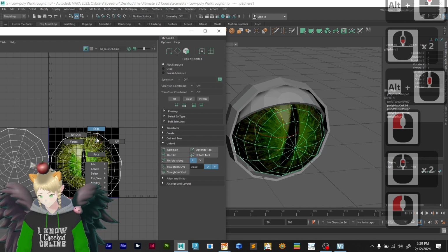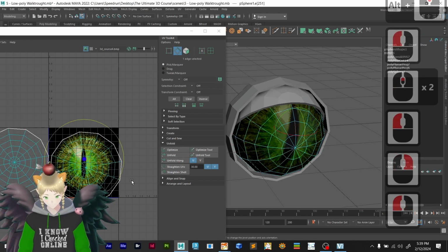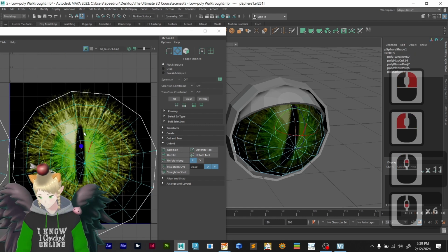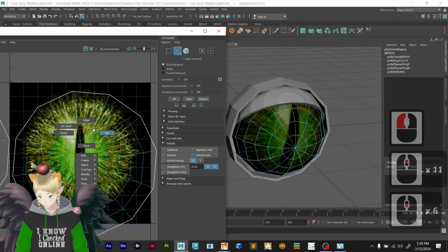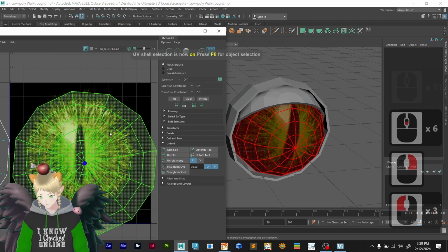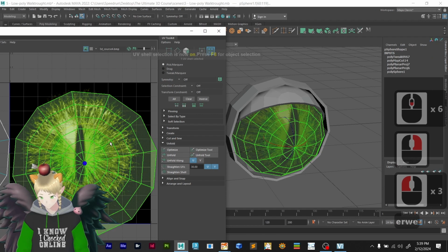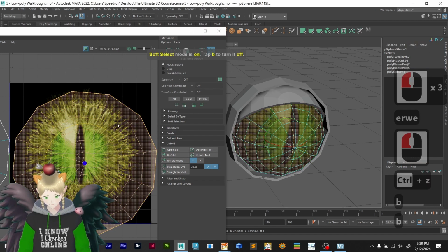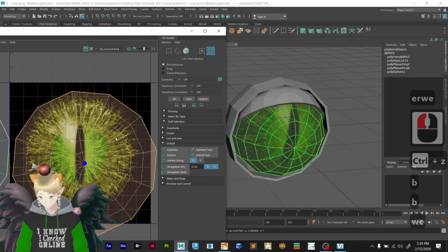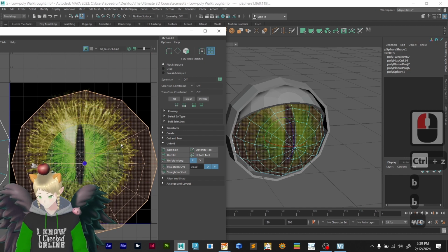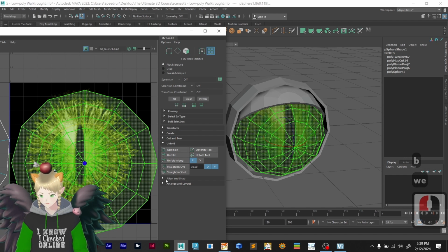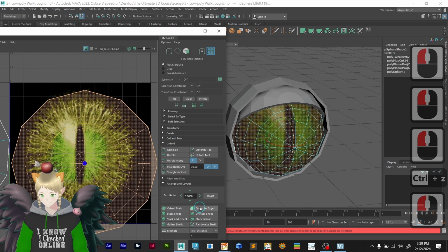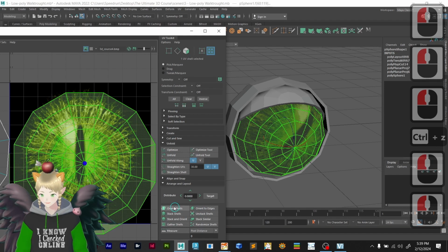I'm going to edges. This edge right here has to be facing straight here, so we need to turn this a bit. Rotate a little bit. Seems like the brush is turned on. Let me see. All right. Let's rotate a bit. And when this line is almost straight, we can go here to arrange layout, orient shells, orient edges. Didn't work. So orient shell.